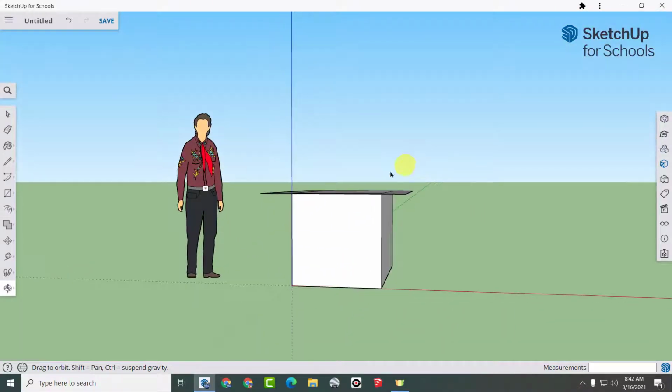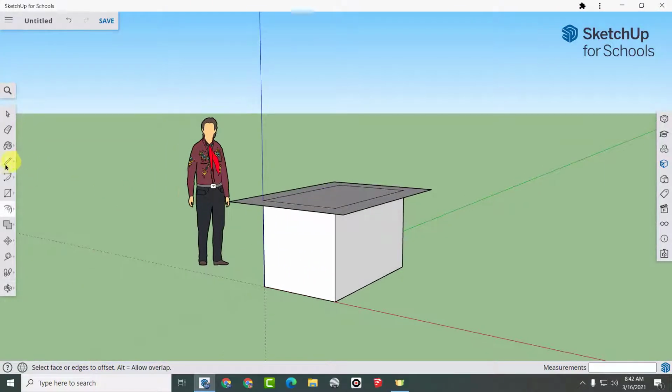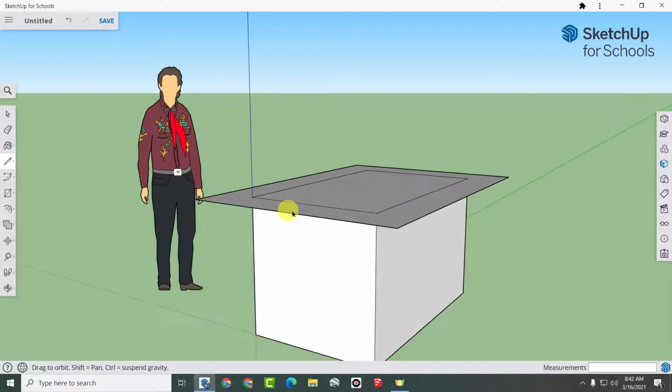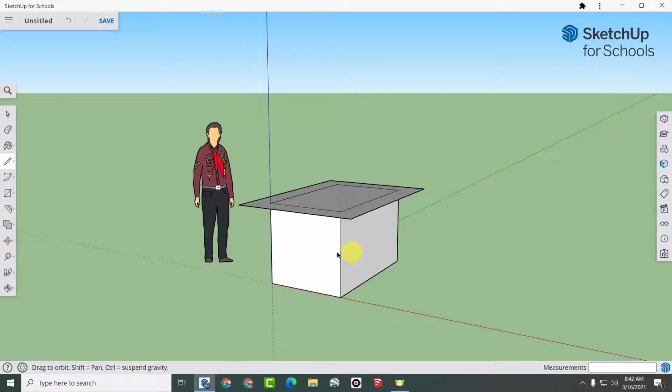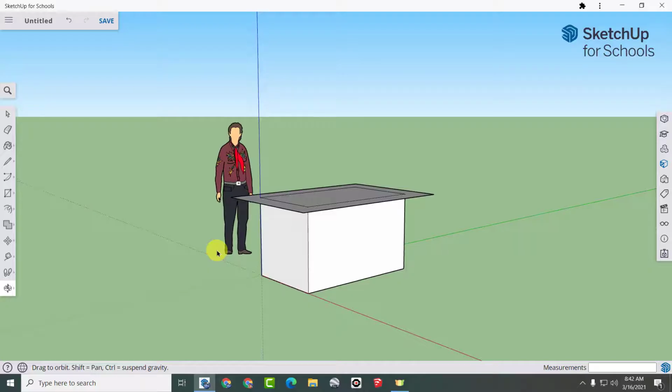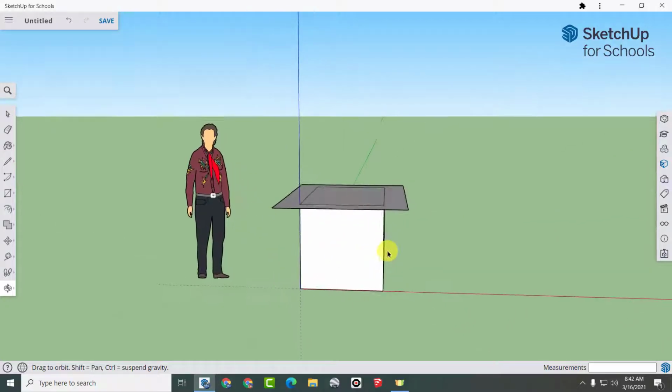All right, now we're going to create the roof for our doghouse. So I'm going to take my pencil tool, and I'll move from the center point, or the midpoint, I should say. You'll notice the midpoint because you get this cyan dot. And notice I'm constantly moving my drawing around by using my orbit tool. It's important that you always have a good view for what you're doing. So you may have to move your orientation of the drawing for what you're doing.